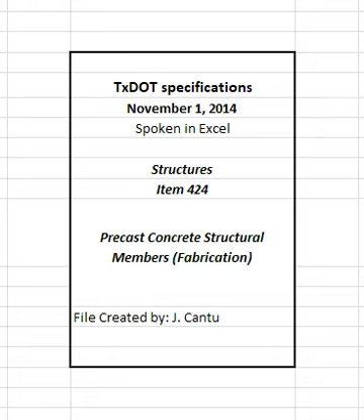The maximum time between the addition of mixing water or cement to the concrete batch and the placing of concrete in the forms is 30 minutes for concrete delivered in non-agitated delivery equipment and 60 minutes for concrete delivered in agitated delivery equipment. If conditions of wind, humidity, and temperature cause quick stiffening of the concrete, the required placement times may be reduced and an approved retarder may be required, or increased if currently in use.